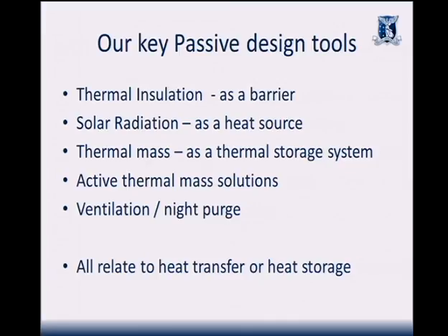Okay, so insulation resists heat flow from one direction to the other. If it's 26 degrees inside and 26 degrees outside, the insulation's doing nothing at all, because there's no flow of energy in any direction. Thermal mass is different though. Thermal mass is not resisting flow, it's storing heat. And like I say, it's always about storing or releasing heat, not about cold. Cold's the opposite of heat. I know you know that, but it's good to understand that. So that's another thing we can use in our system or our toolbox to create a comfortable building.